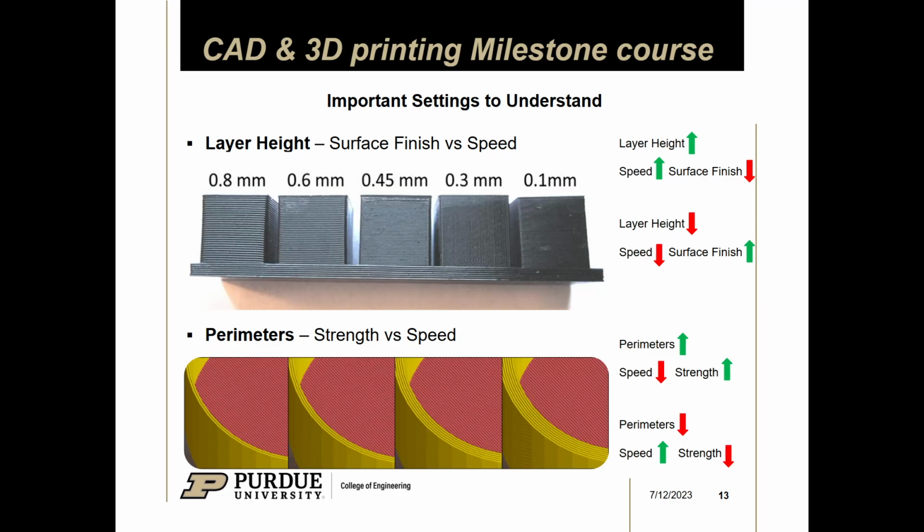So now that you kind of understand the concept of 3D printing, there's a bunch of different settings that can be applied when you go to 3D print something. The first one is the layer height. Basically, how the 3D printing software works is it takes your model and slices it into a bunch of 2D profiles, and then it'll stack the layers on top of each other until you have your part. So that's why it's called a slicer, if you're curious. It'll slice your model, right?